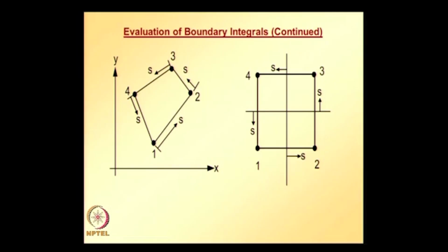And shape functions for each side of the parent element can be written by substituting the constant coordinate into the shape function expressions. You already know the shape functions of the 4 node quadrilateral element in the parent element domain S and T. In that, shape functions for each side can be written by substituting the constant coordinate value into the shape function expression.